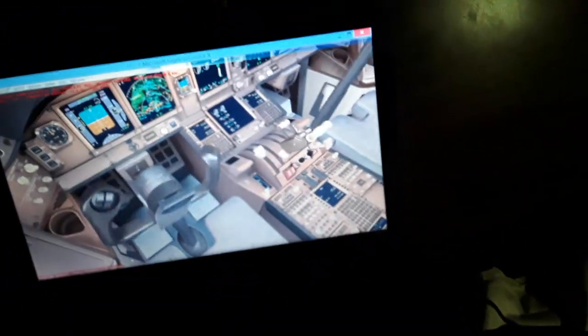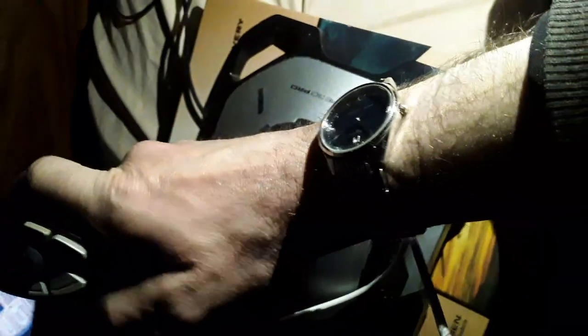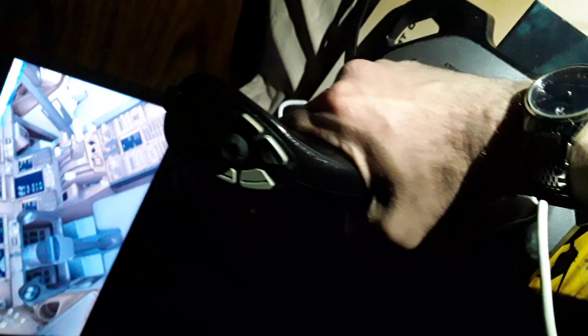You can see inside the cockpit we control the yoke like this and the rudder pedals for steering the aircraft. So I'm having this side stick here, the Logitech Extreme 3D. For the simulation you can leave it in the neutral position. For the flight controls you can move it up for climbing, use the elevator up, use the elevator down for descent, bank roll left and bank roll right. So you see the position of the side stick is proportional to the position of the flight controls inside.